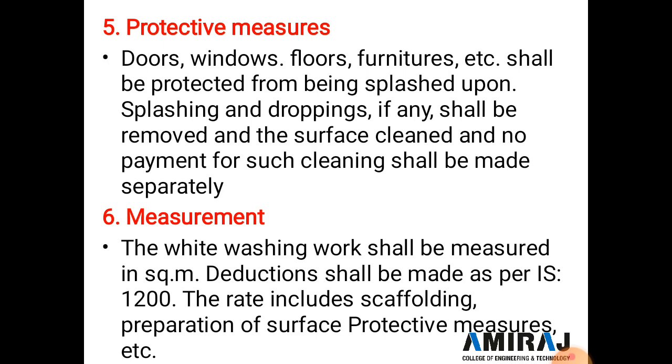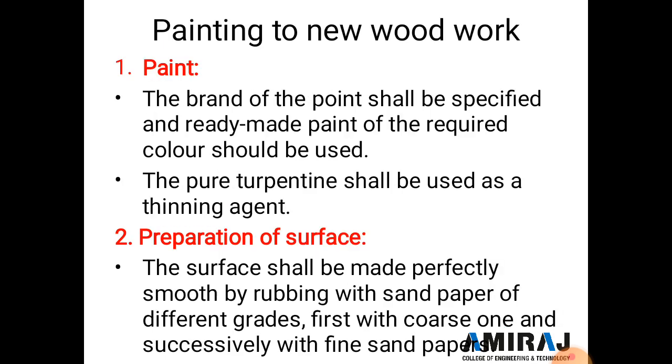Now the sixth specification for whitewashing is measurement. Whitewash is measured in square meters, and deductions shall be measured as per IS 1200, and the rate includes scaffolding, preparation of the surface, protective measures, etc. included in the measurement.